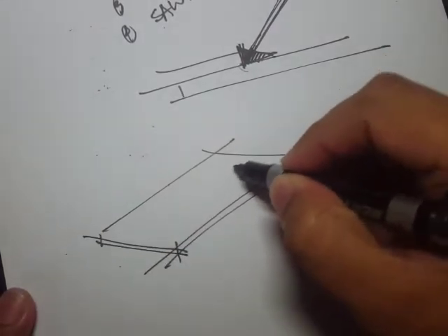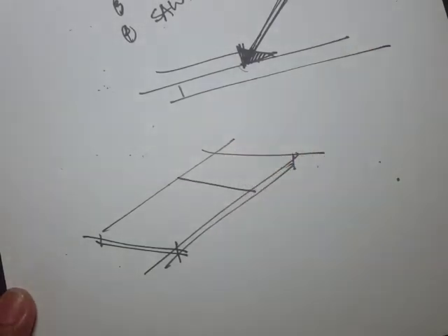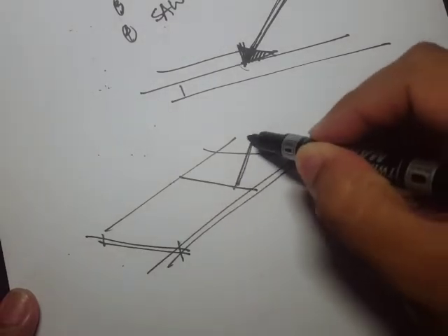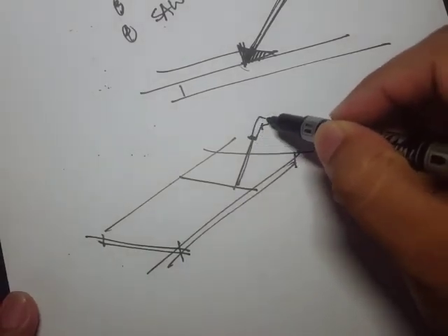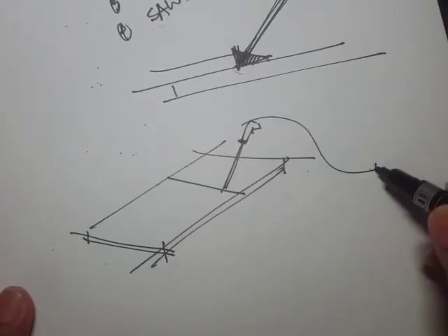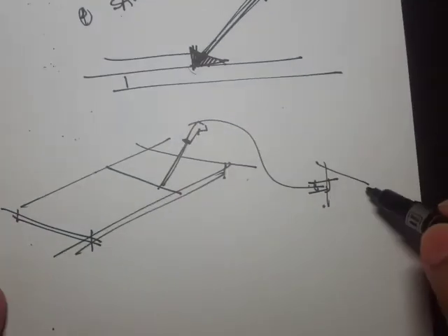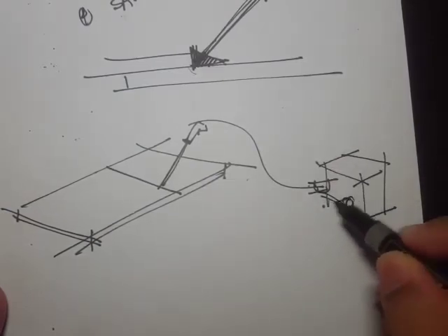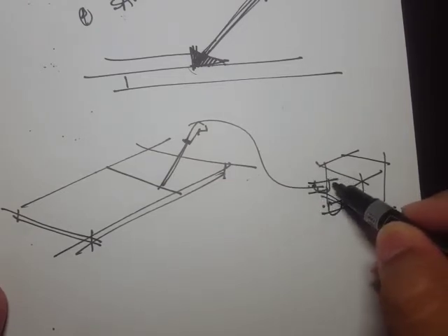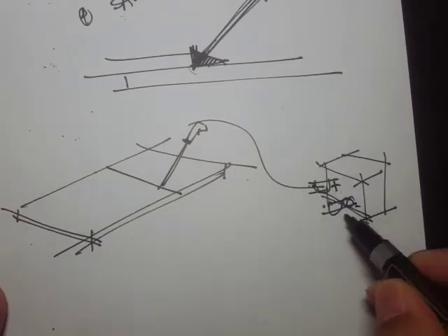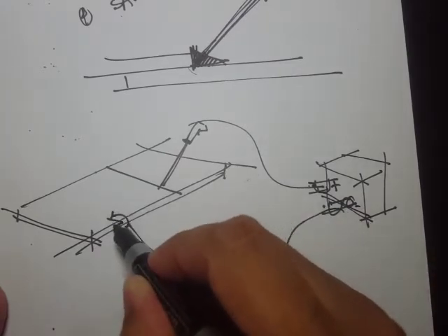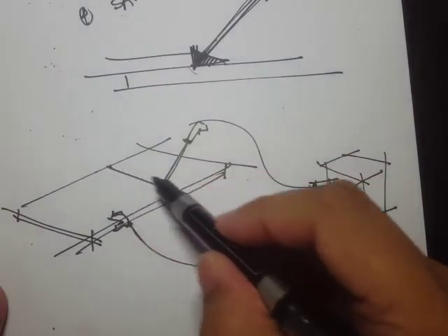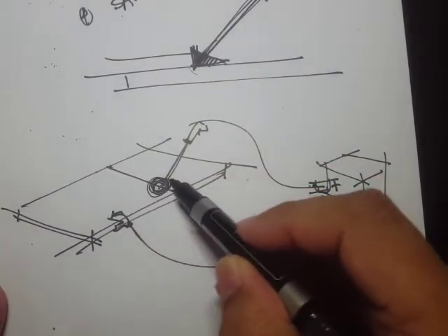Let's say this is our joint, and to join this we have these electrodes, and this electrode is connected to a holder. Then this holder is connected to an electric welding machine. There's a positive one here, I think this is the positive, and the negative, the ground, is clamped on the workpiece. In that way it can produce an arc over here.